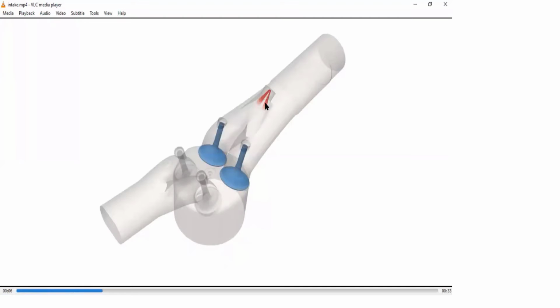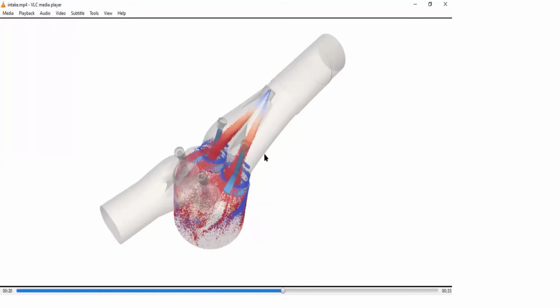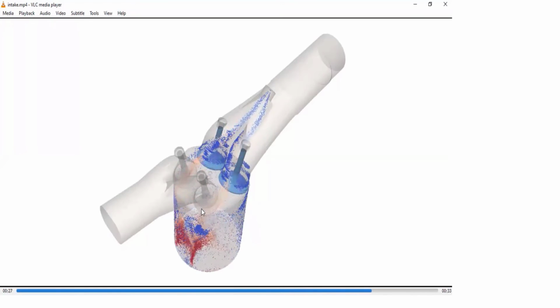I'm basically injecting fuel in the form of spray. This is how the injectors will spray the fuel into the port fuel injected engine. So this is basically where the importance of spray will come. Fuel came, intake stroke started, mixed with air, came into the cylinder. These are two intake valves, two exhaust valves, cylinder, liner, exhaust port, intake port, injectors, fuel getting sprayed, mixing. That's it.